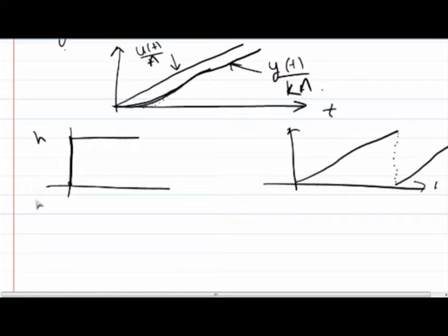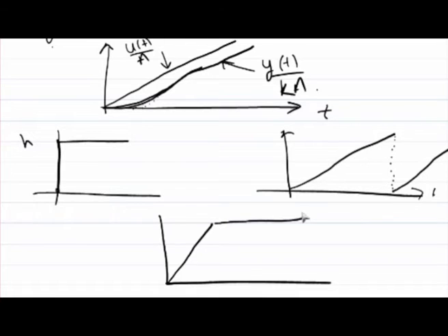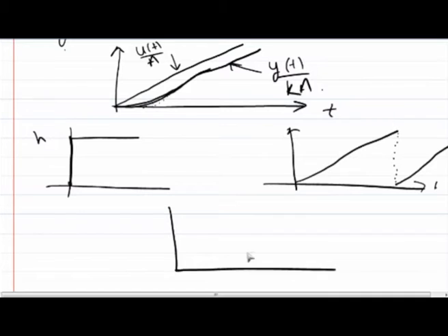I need to slowly excite the system in a ramp fashion so that it reaches the 500 value. Afterwards, it could stay there for a longer time. So for this reason, generally we require this ramp input for the startup of the process.